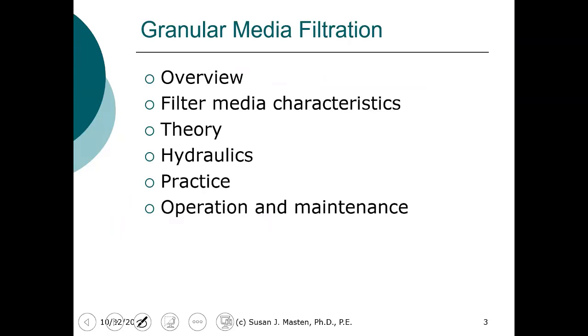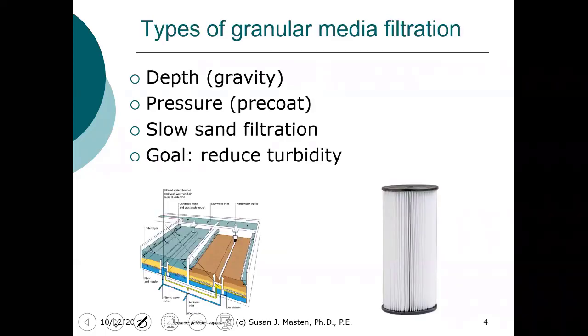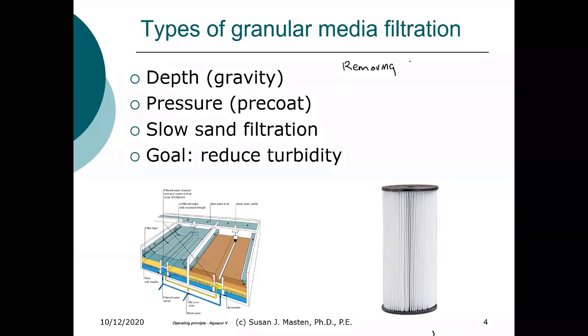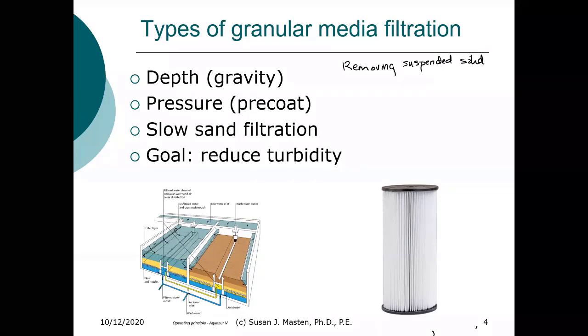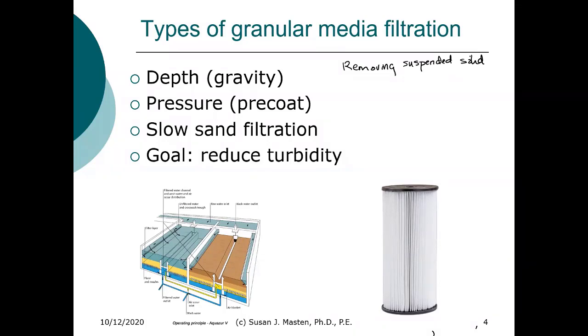We'll look at media characteristics. We'll look at some theory. Much of what we will be focused on is the hydraulics of both filtration and what we refer to as backwashing. So when we talk about granular media filtration, the focus really is on removing suspended solids. So granular media filtration most often follows some sort of coagulation, sedimentation, unless it's a very, very pure, clear water, in which case you can use direct filtration. But the goal is removing suspended solids.